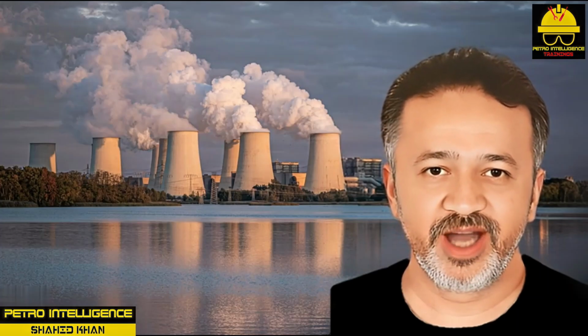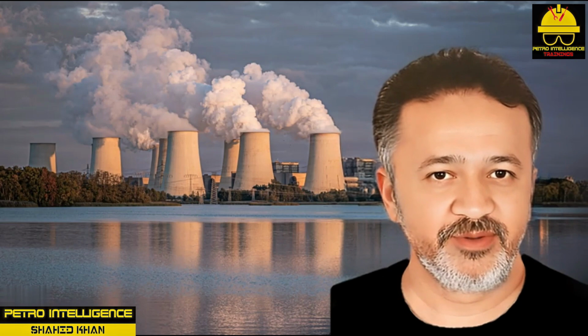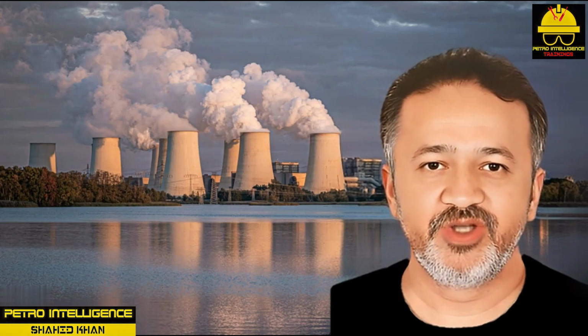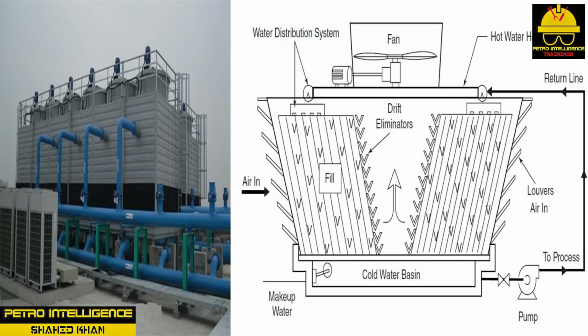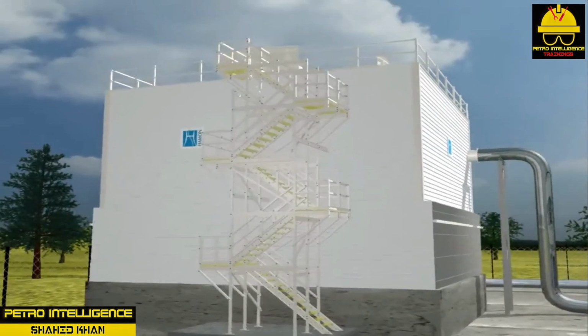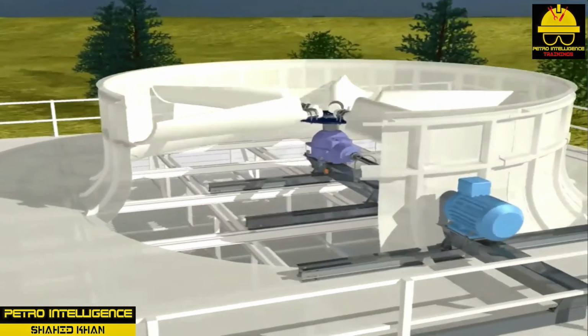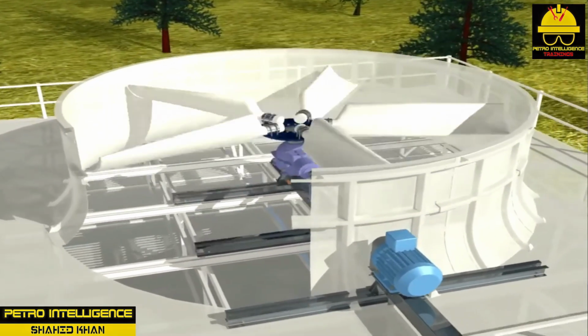Induced draft cooling tower. An induced draft tower is another kind of cooling tower that produces airflow mechanically, as shown in the picture. It differs from the forced draft cooling tower in that it pulls air out of the tower rather than forcing it in. Airflow in an induced draft tower is slower than in a forced draft tower, but heat transfer through evaporation is more efficient.